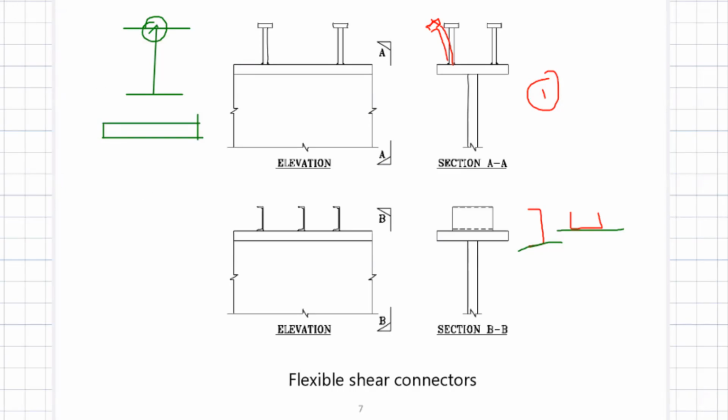Now, what is the shear equilibrium for me is that the flange has a force, right? That force is transferred as shear in the interface. That is what we have already learned. Even for a simple plate girder, three-plated system design, we find what is the force coming on the flange.